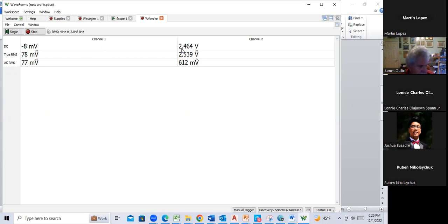That tells me that I wanted my collector current to be 1.26 milliamp. It looks like it's 1.73. Okay, and let's just for kicks see where my base is right now. Let me move that probe, that's the orange one here. So if I move it directly onto the base, that says my base is about 1.46. That's a good place for it.